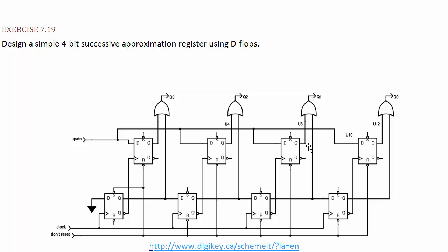Okay, so when each of these goes from 1s to 0, they trigger these. That's the only time these get triggered on the high pulse, because there's no inverse of this input. Since it's hooked up to the inverting output of these bottom flops, it triggers when the bottom flops go from their 1 state to their 0 state. So we get one shot to permanently store in whatever the digit should be. That means that before that happens, we have to be comparing to the appropriate bit.